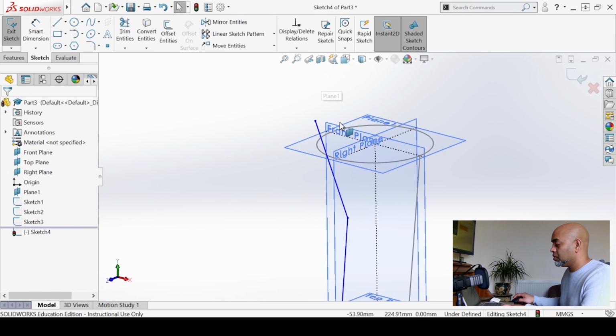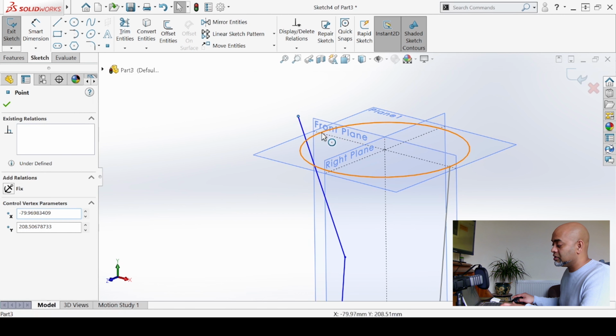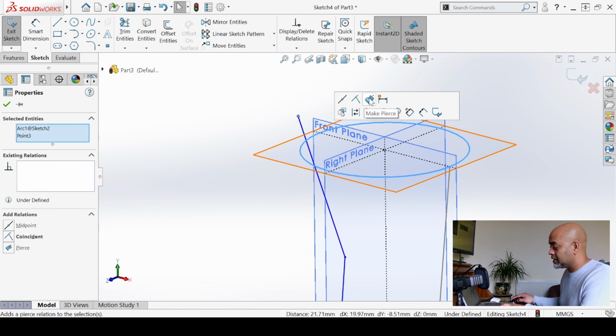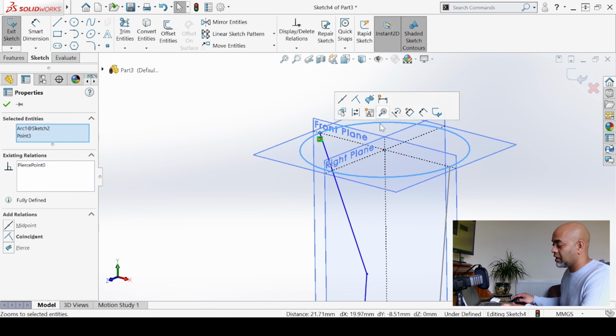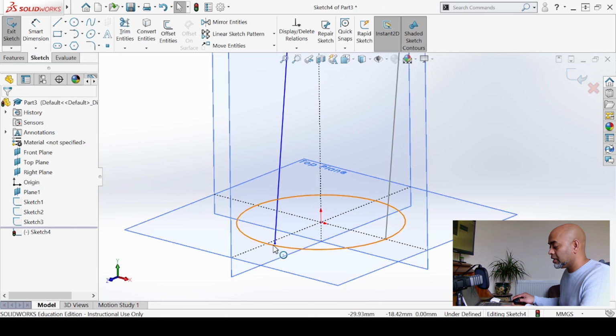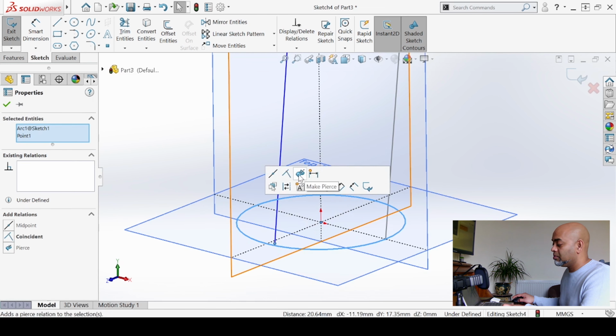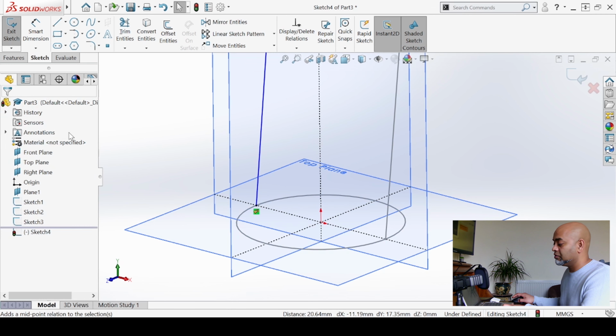Once again, I'm gonna make sure my line work is tight and they're all connected. So I'm going to go multi-select and pierce those things together, and I can do exactly the same around this way. So select that, Control select the circle, make sure they're piercing, green tick to confirm.